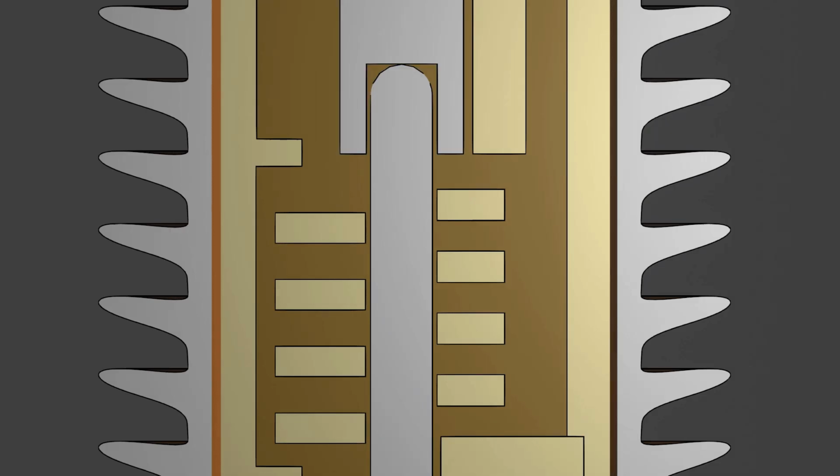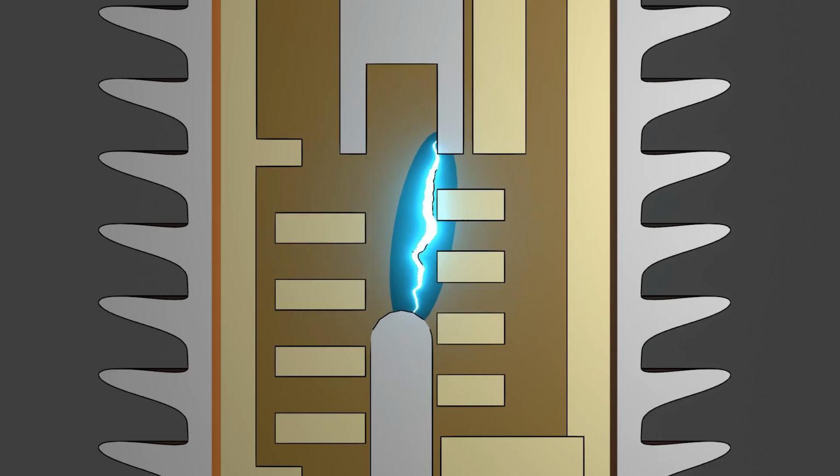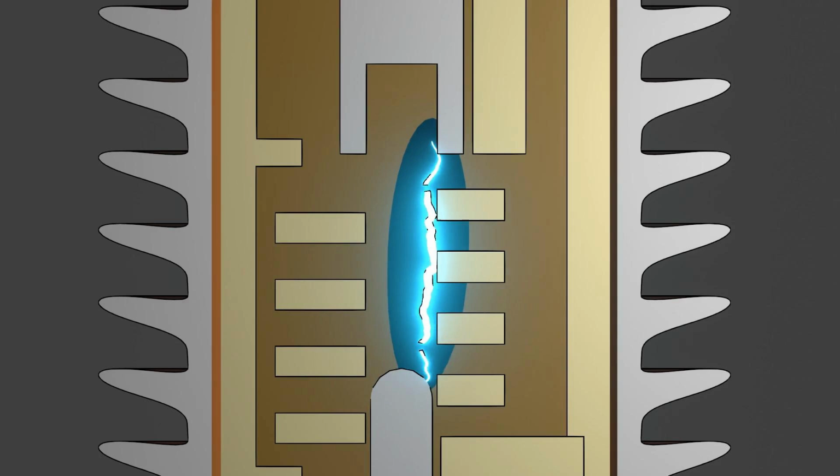During opening operation, the moving contact moves backward. Therefore, the arc starts between the fixed contact and the moving contact. As the moving contact goes away from the fixed contact, the arc length increases. Thus, the quantity of hydrogen gas produced by the arc also increases. As a result, the size of the bubble increases while the moving contact moves backward.